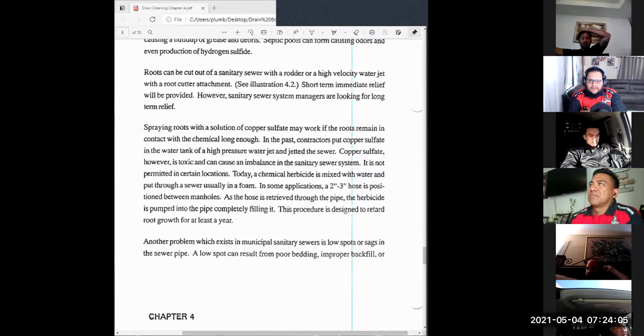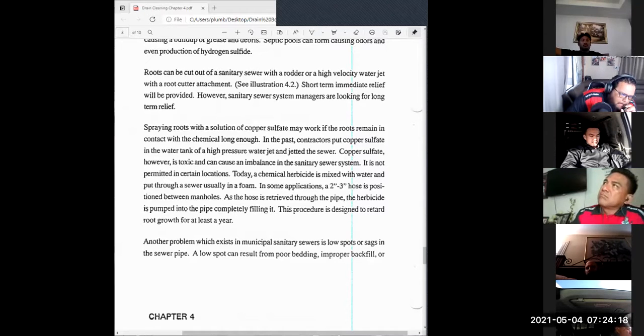When we went back 6 months after, what, Brandon, was it 6 months? Yeah, just about 6 months. What would you say the result of the vapor rooter was? So when we initially cameraed, we saw roots still, and we were thinking, oh goodness, it's still there. But when I started pulling back my camera, I noticed those same roots that looked healthy were all dead. They were just disintegrated, almost crumbled. So we just jetted out all that debris, and that line was pretty much free and clear right after that.